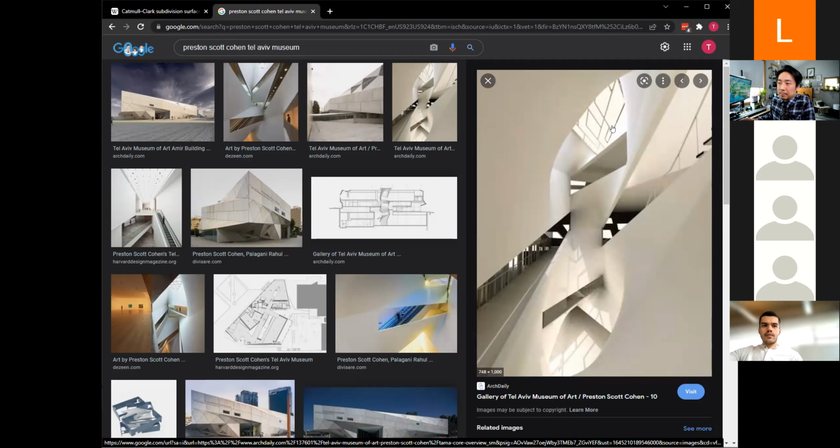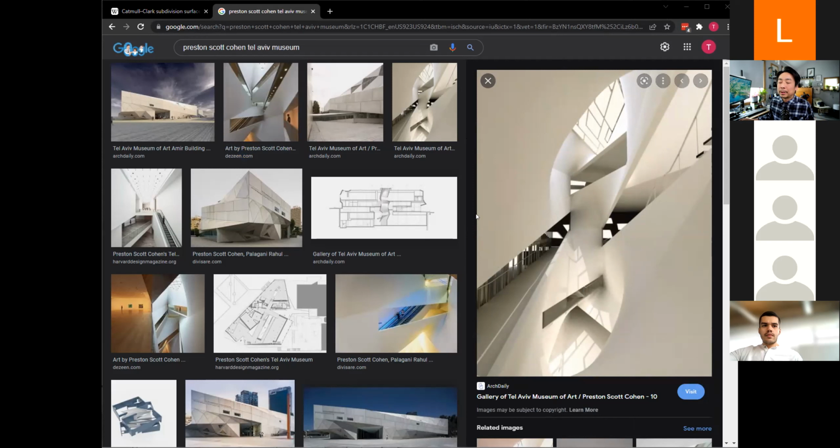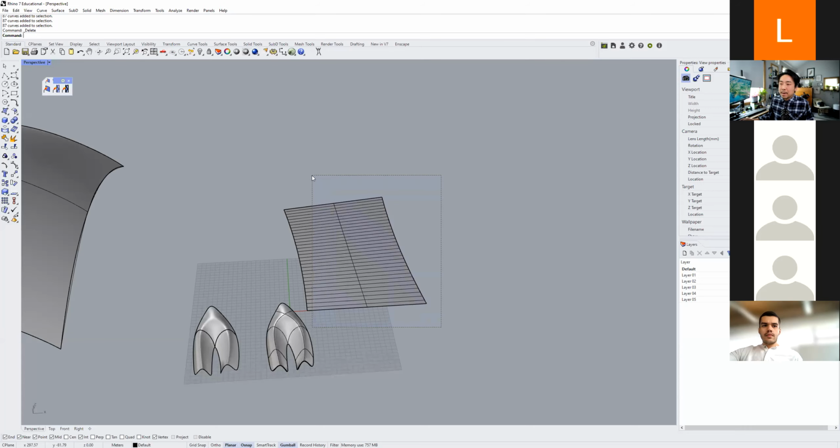It's this sort of atrium, skylight space. So every single surface is curved ultimately, but they are singly curved. So it's very, very easy to manufacture. What that means is, to recreate that curvature, you simply use straight studs and drywall, and use patch stucco to make the seams a little bit smooth, but it's extremely easy to construct. It's the same construction method that the TWA terminal and most other contemporary buildings are made with.